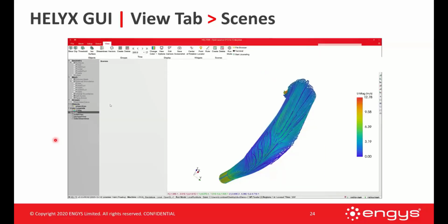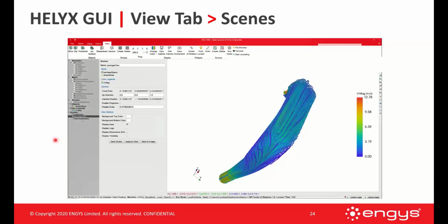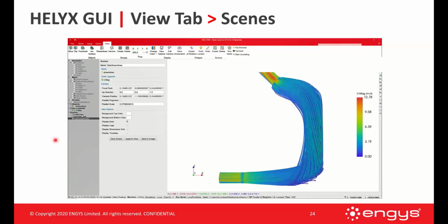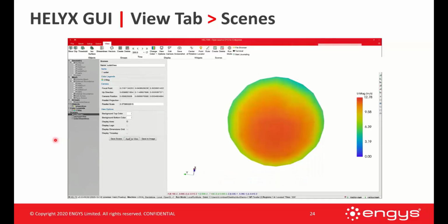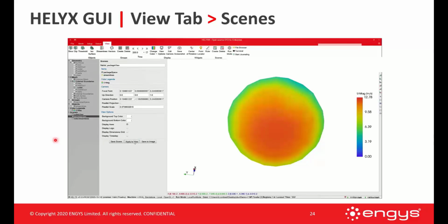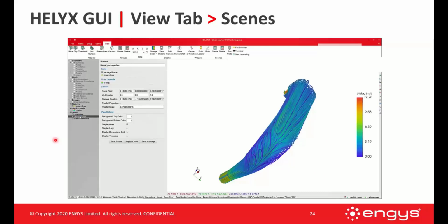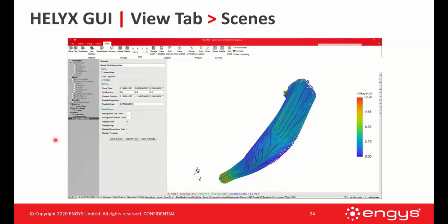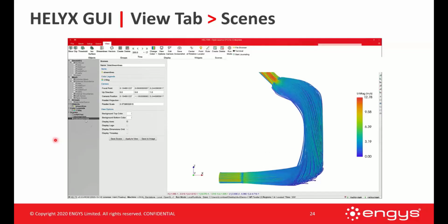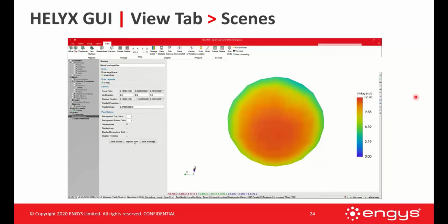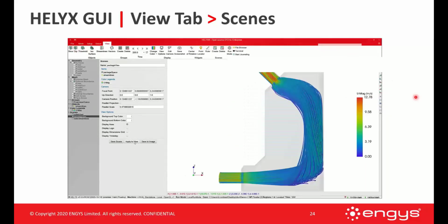The benefit is that if I rerun this simulation on a finer mesh, or extend the time scale, or change the end time, I'm able to consistently get an image from the exact same angle from that same simulation. And if I clone this case and rerun it on different configurations, I can keep the same scale. So it allows us to have one single environment to go from meshing all the way to view, and to have the same images every single time.